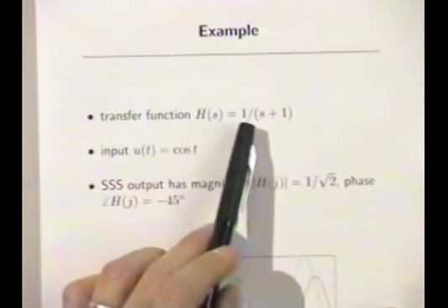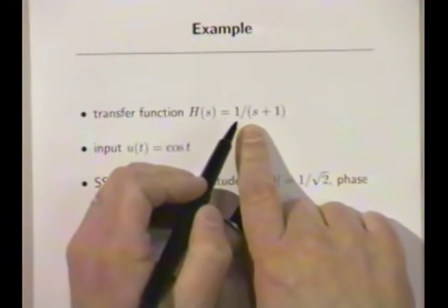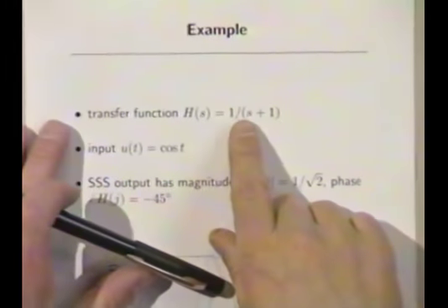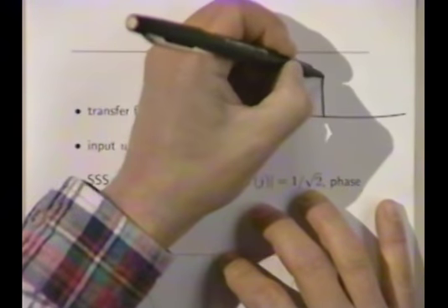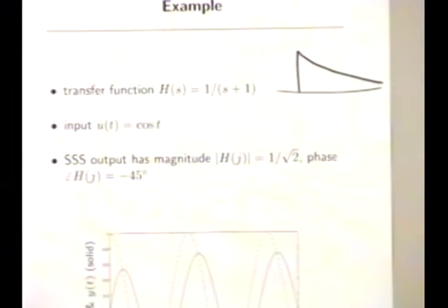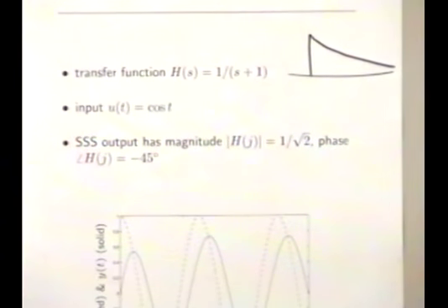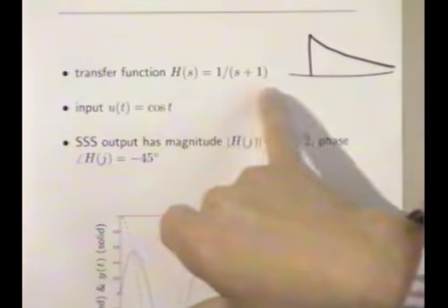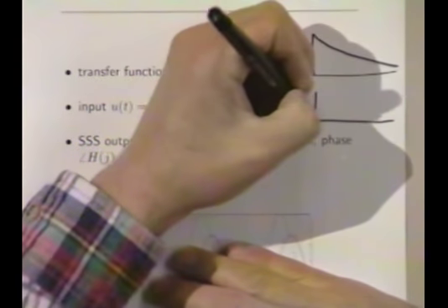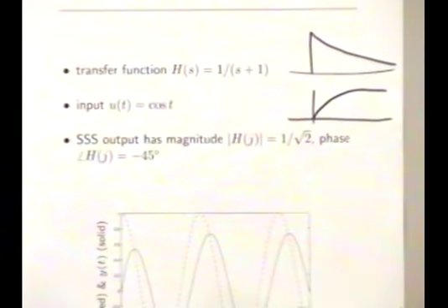So let's look at an example. Here's an example. It's a low-pass, single pole transfer function, 1 over s plus 1. Impulse response is this decaying exponential. Sometimes people call that an exponential smoother. People call it a discount rate in economics. It has all sorts of different names. I guess in electronics you would call this a first order, single pole filter, right? And you have a rough idea from 101. The step response is your old friend, this thing. That's your step response, and so on.